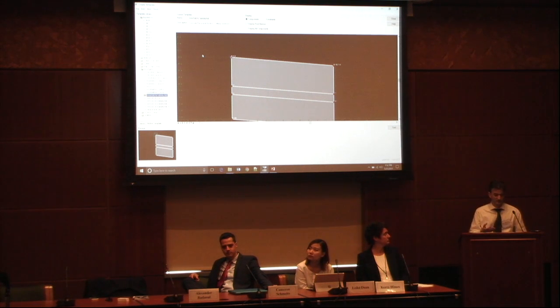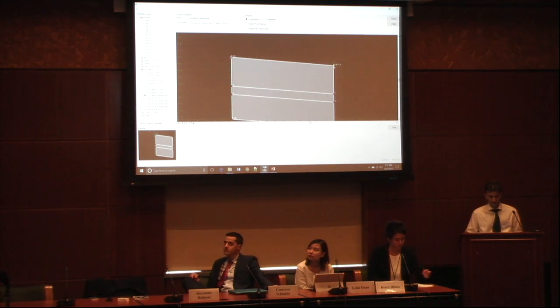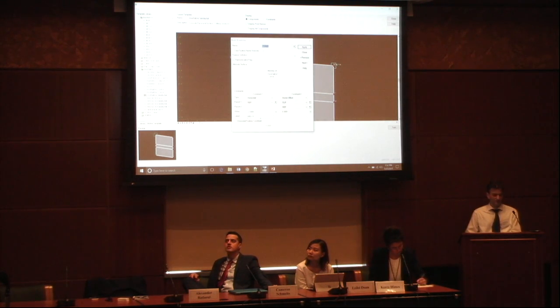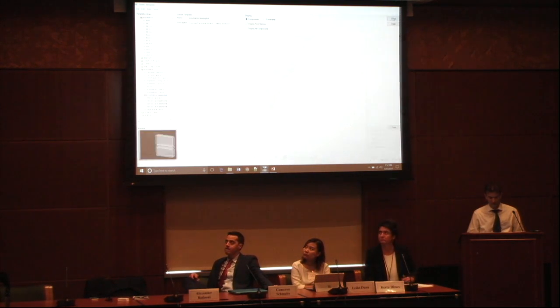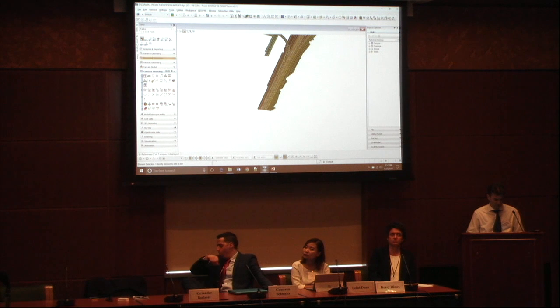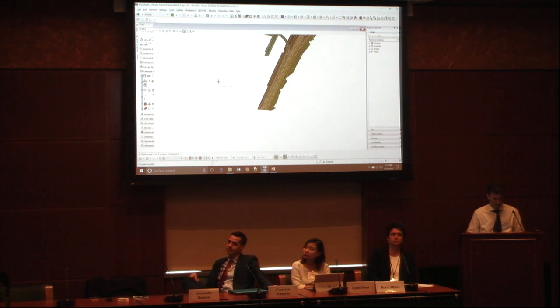The other way to control it is each one of these points can be controlled via a parametric constraint, which the program can read. So that width value, by default, is going to be reported as 12 feet to the right because it's 12 positive. If I want to change it, I insert the template into the program, and then it comes up with an option known as a parametric constraint, which is here.